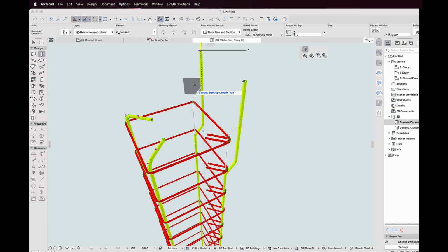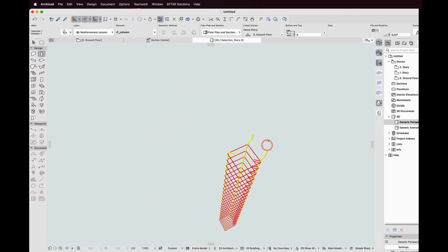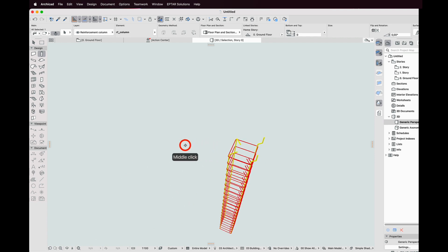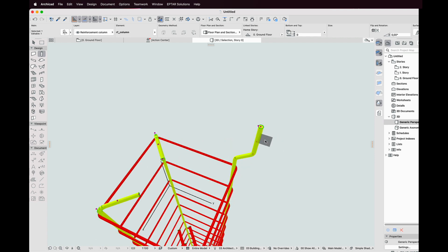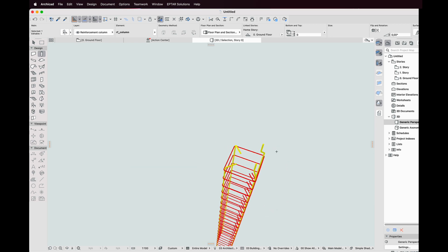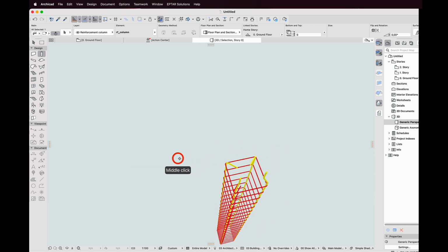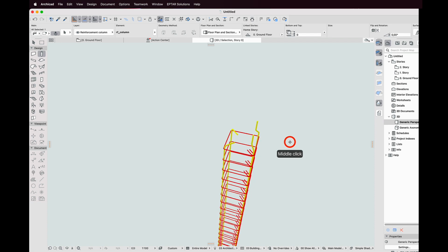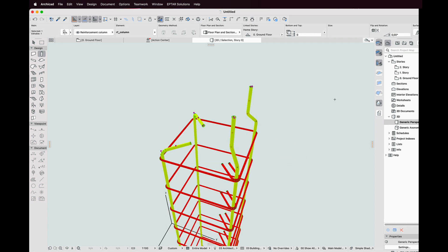But I see again, the direction of the bend is wrong. With the hotspot on the perimeter of the rebar section, I can turn the rebar to the correct direction. The second rebar in this group will be turned too, but of course symmetrically. With this method, we get a much better solution for creating column reinforcement continuity. Of course, the simple bent rebar can also be stretched longer with the hotspot defined in the corner of the bend.